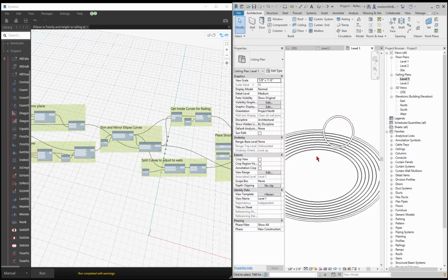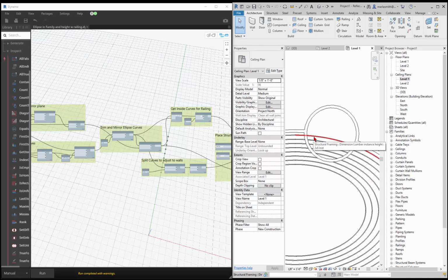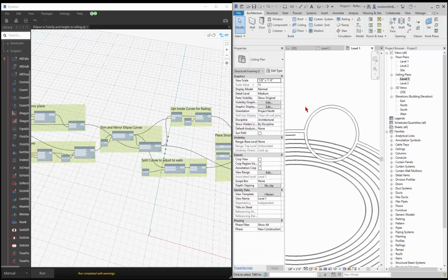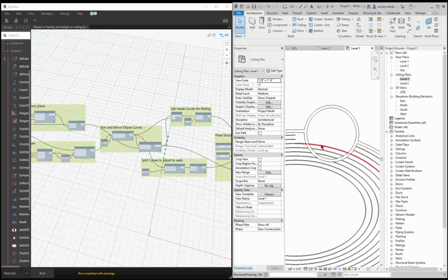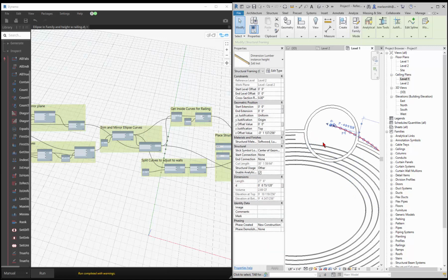So if you want to pull these beams out, you pick them, and for the ones that get shorter, you can use these little arrows and just pull them in, and it'll pull them back. If I pull this back, one thing you want to be careful about is there's also a little blue dot that you can grab, and if you grab that, it's actually going to adjust the ellipse, and we don't want to do that.